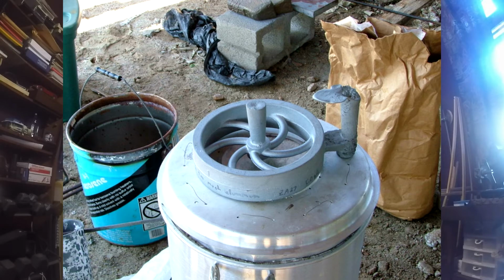You can get an idea of what it might look like if you look very closely at the bottom of the sprue where the splash basin is. It's not smooth like above the splash basin. It's all messed up with holes and pits in there. That's a good indication that right there is a bunch of dross that was formed. And because that sprue wasn't tapered at all, you know that gating system was never pressurized. So every moment that they were pouring that, they were manufacturing dross.